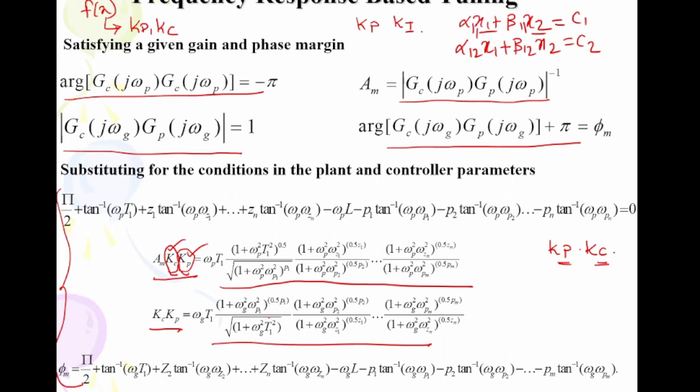Okay, right. So most of the times when you are designing a controller, like here for this particular problem, we have designed a controller so that a particular gain margin and phase margin is obtained. So these equations you have written from the knowledge that you have regarding the control system. And once you have written the equations, then you forget about the control system. It is a pure mathematical problem. If you give these 4 equations to a mathematician and tell him, get me the value of Kp and Kc for which all these 4 equations are valid, that person may not have any knowledge about control systems, but that person will provide you the solution. But if your equations are incorrect, he will provide you the actual solution, but with that solution, you may not attain your objective of the desired gain and phase margin. Desired gain and phase margin basically means the specifications of the control.